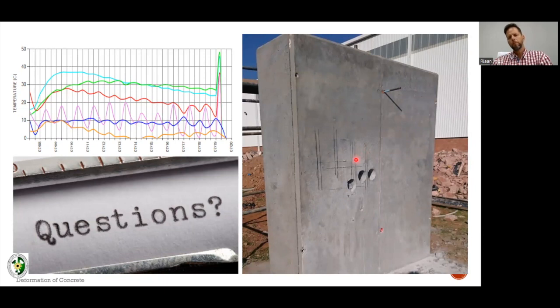And then they start to drill the first core and they hit rebar. Why did they hit rebar? They brought a little metal detector, but this concrete has some steel fibers in it. Not much, about 40 kilograms of steel fiber. And they couldn't find the rebar or find a spot without rebar. So they did some exploratory drilling over here. So the first rendition, they hit rebar and they were able to start drawing them out. And they started measuring 200, 200, 200. And then the second one, they aimed to try and miss it. They hit rebar again. And then the third one, they got lucky.